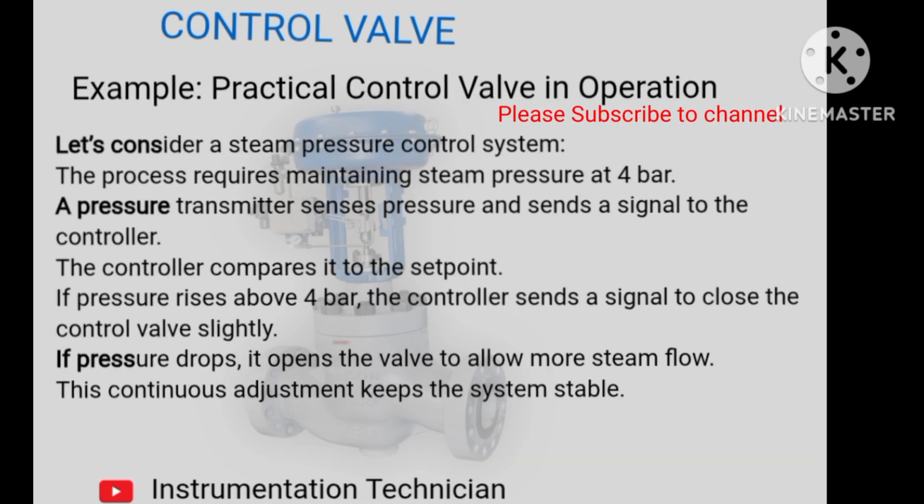Example. Practical control valve in operation. Let's consider a steam pressure control system. The process requires maintaining steam pressure at 4 bars. A pressure transmitter senses pressure and sends a signal to the controller. The controller compares it to the set point. If pressure rises above 4 bars, the controller sends a signal to close the control valve slightly. If pressure drops, it opens the valve to allow more steam flow. This continuous adjustment keeps the system stable.